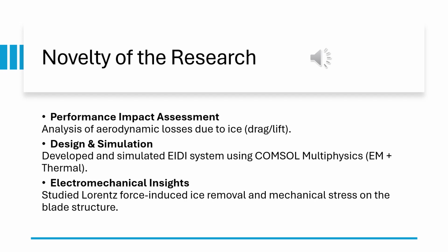Next, what sets our work apart is the multidisciplinary approach we use to understand and simulate ice mitigation. First, we conducted a detailed performance assessment showing how aerodynamic properties, especially lift and drag forces, are altered under ice conditions. Next, we designed and simulated the EID system in COMSOL using both electromagnetic and thermal modules. This allows us to visualize how magnetic pulses behave in real turbine materials and how these forces can be used to remove ice without thermal melting.